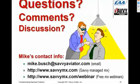And the only other thing that could be wrong is that when you turn off the battery switch, somehow voltage is still being applied to the battery contactor coil, and that would either be a defective master switch, which would be pretty unusual, or sometimes there's a diode or something across the battery switch for arc suppression, and I suppose it's possible that the diode might be shorted. But it sure doesn't sound to me like a battery contactor is a very likely explanation for this.